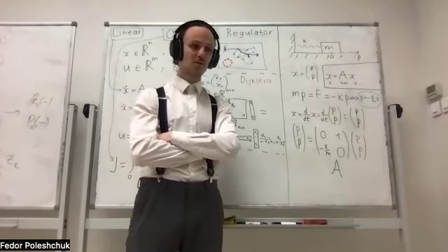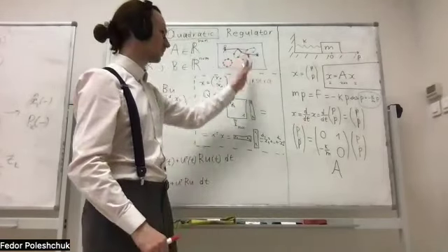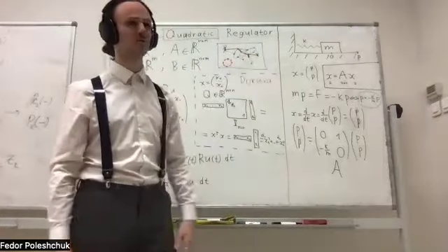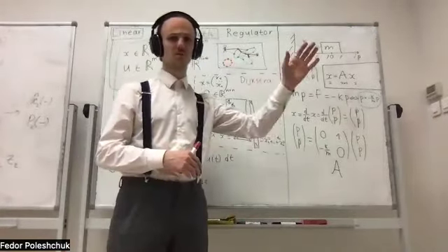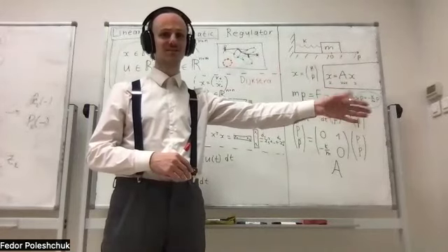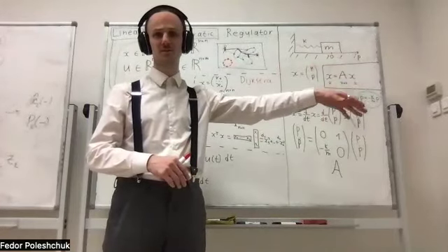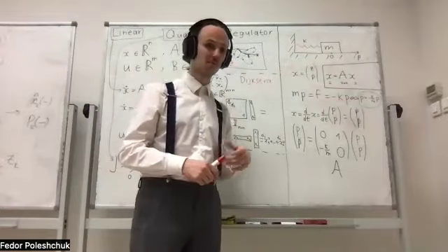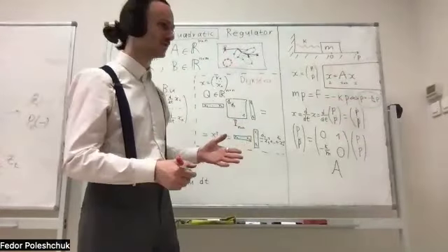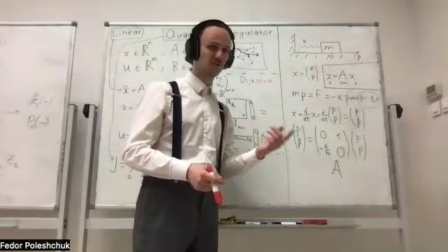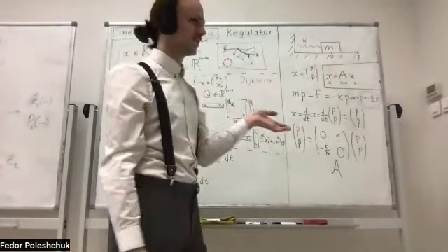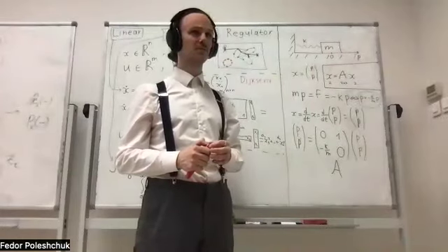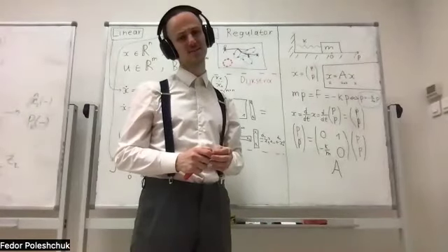Also, we cut this process of considering obstacles by half of the field, because if something is very distant, that doesn't concern us much; the situation will change before we get there. So 3-4 obstacles, 24 or 32 points, and 2 points here. And this graph search works pretty rapidly, like tens of milliseconds on this CPU.